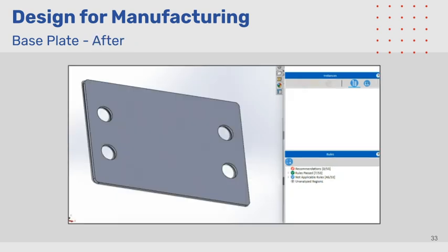The base plate was modified as per DfM Pro guidelines. First, the wall thickness was reduced from 10 millimeters and made constant throughout the plate at 3 millimeters. This lowered material costs. Additionally, draft angles were added to increase manufacturability. These draft angles were 5 degrees along the exterior edges and 1 degree for the holes, as suggested by DfM Pro. The operating cost for this model is 2 cents. The mold cost is $1.70 given the production volume of 50,000, and the material cost is $1.29. The sum of these costs is the total injection molding cost for this part and is $3.01. This represents a 40% cost reduction from the original design production cost.